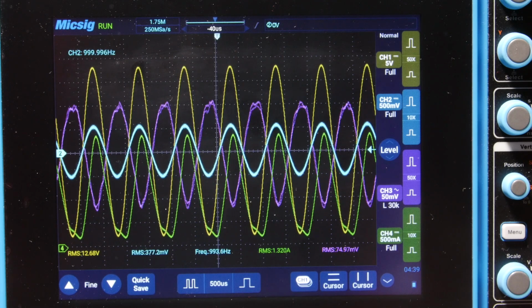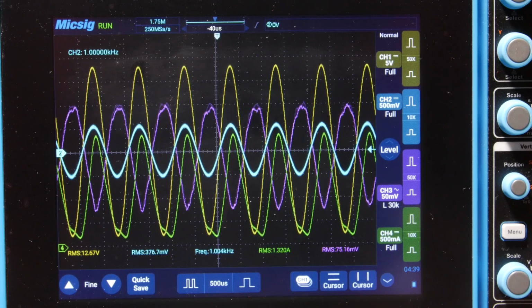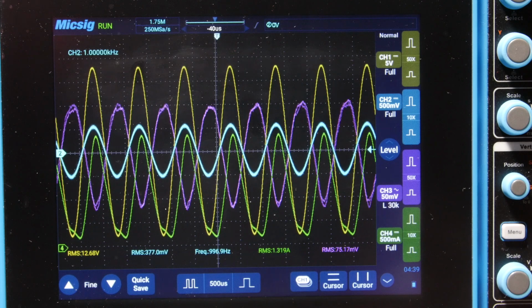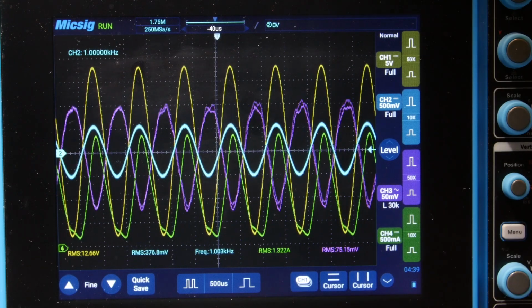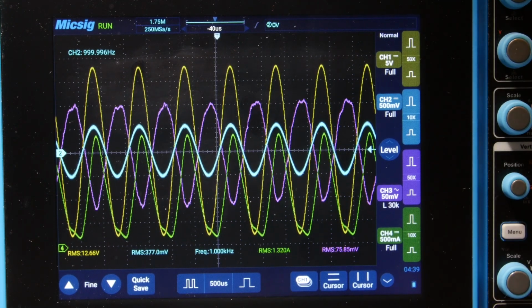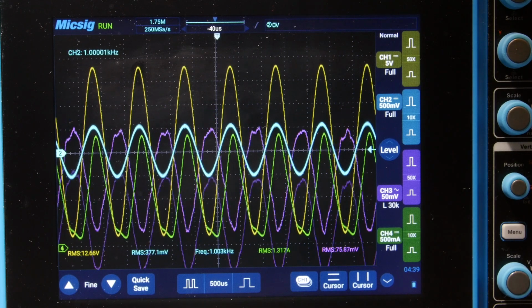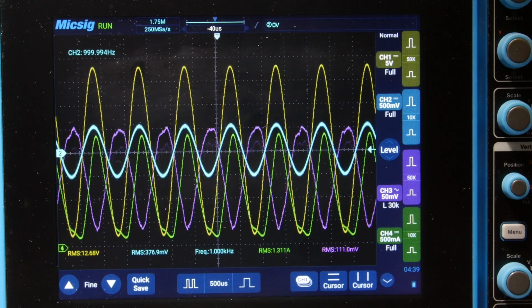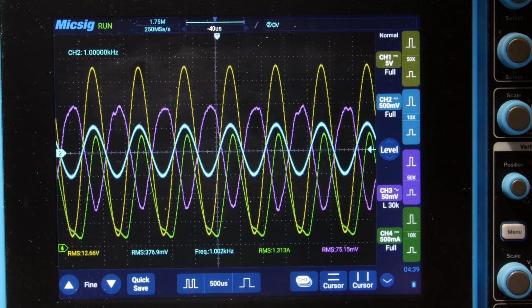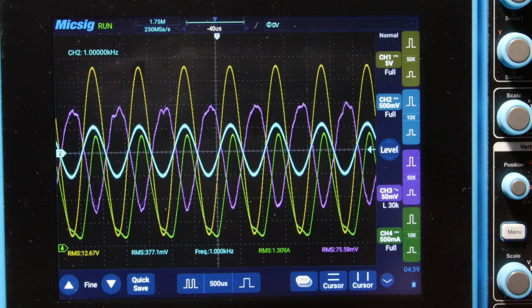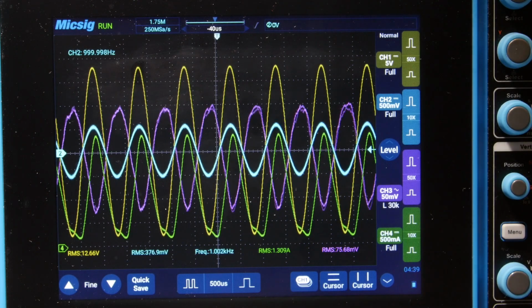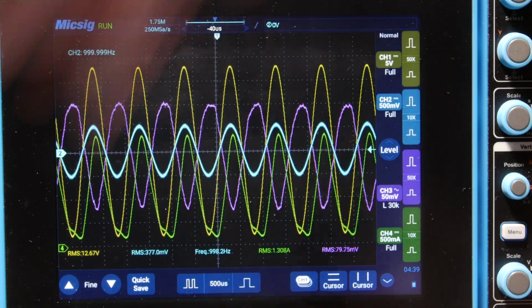Okay, so now I'm at 31.6. My THD is about 0.03, and I think a lot of that's coming from the Unity, the generator. But okay, I'm going to go ahead and drop the lab supply until I see it affect the THD. And what I find is I'm at 29 volts right now, and it's still well above.